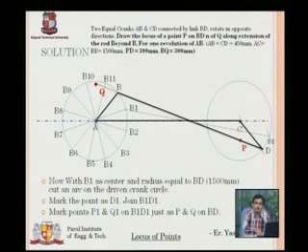Now I need to mark my position of Q and P. So I'll extend it. This is my Q1, and I will cut an arc at P1. So this is my P1. How did I do that? The same way as I marked Q. From B1 I'll extend the rod D1 B1 beyond B1 300 mm and mark point Q1. Then how will I mark P1? With center as D1 and radius equal to PD, that is PD is 300 mm again, I'll cut an arc on B1 D1 from D1 to P1. So I'll get the position of P1.